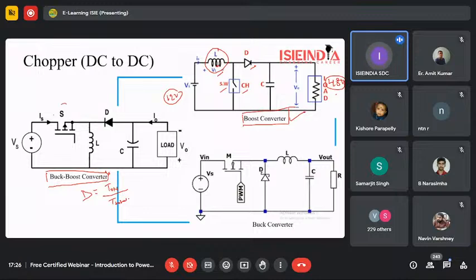T total is the total time period of the switch. So the switching frequency, and also the turning on and turning off of these switches, is responsible for the step up or step down operation of these choppers. So these are the choppers. This one is the boost converter. Just remember the circuit: this is L, this is S, and this is D. And here in this chopper we have S, L and D. And talking about the buck converter, we have the switch, this is the D and this is the L.